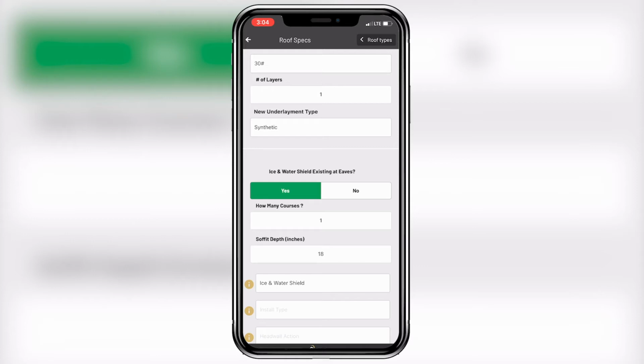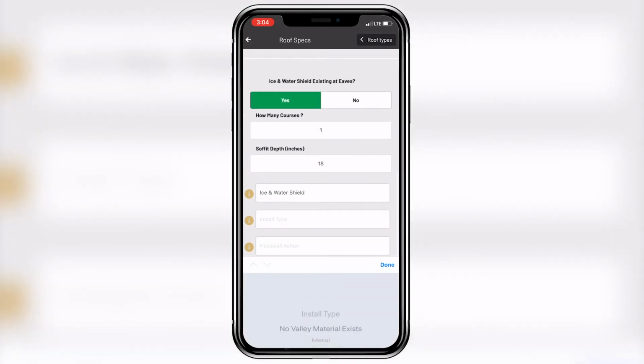So when you have a roof that has a valley, make sure to go to the edge of it, pull up those shingles and see what's existing, and take a good photo of it. As long as you get that photo, we can have it thrown in the estimate. It'll get paid for every single time.